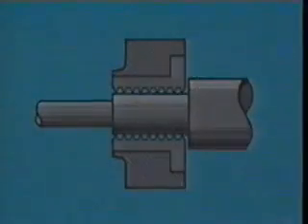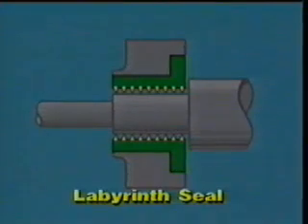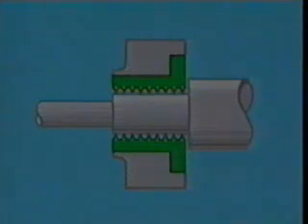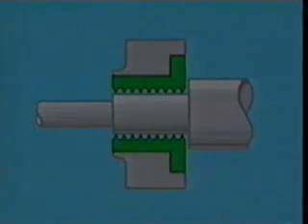The simplest type of seal is the labyrinth seal. It has a series of grooves machined to sharp knife-edge thickness that maintain a close clearance to the mating part. It can either be stationary or rotating. The mating parts are made of a softer material such as babbitt, so they will wear before the labyrinth does. Labyrinth seals can be found in multiple, step, and interlocking configurations. Sometimes carbon rings are included with the labyrinth seal.